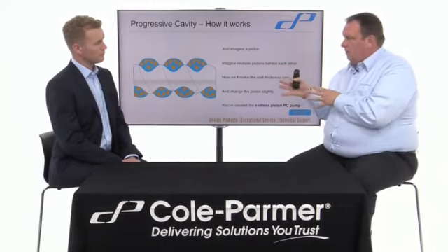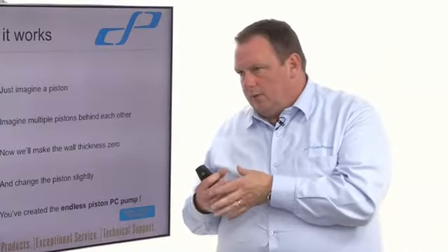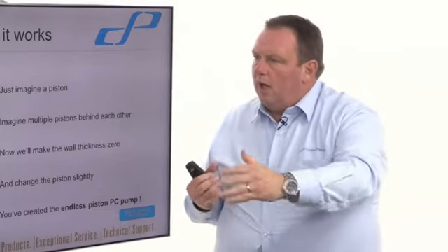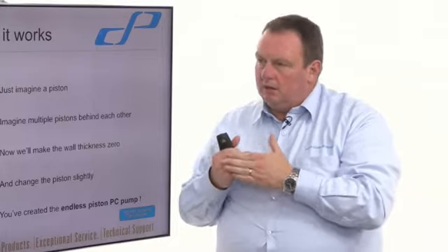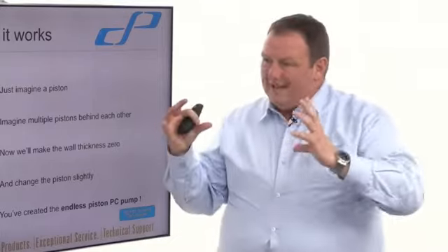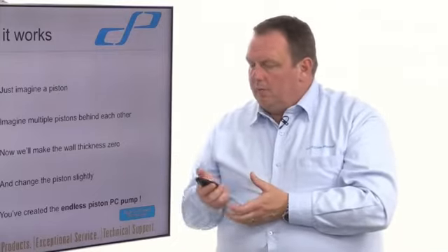So as I said, there is potentially another option of what can pump these things, but it can't achieve the same pressures. These can go to greater pressures, and you're talking in excess of 10, 20 bar in certain instances. It's down to your sealing arrangement, it's down to the motor driving it, it's down to the length of the rotor and the stator. So if you wanted to get a greater pressure, you could have a longer rotor and stator. You have to go bigger on a very specific scale to get the greater flow rates, but as I say, they're very good at what they do.